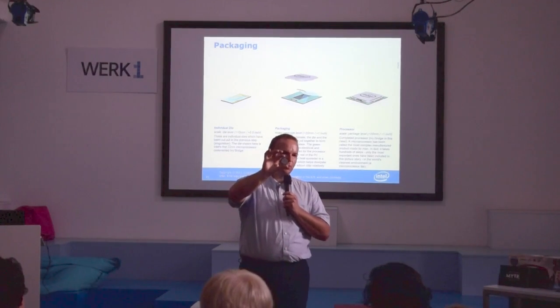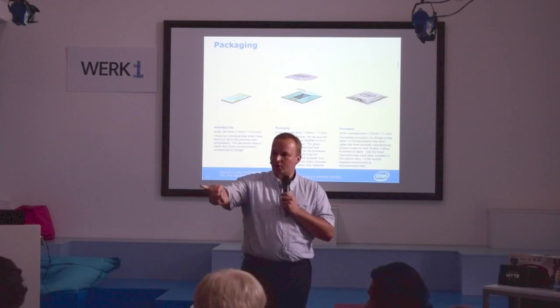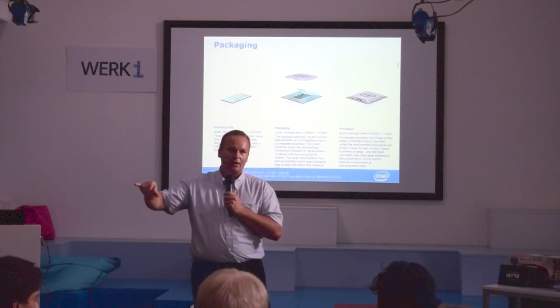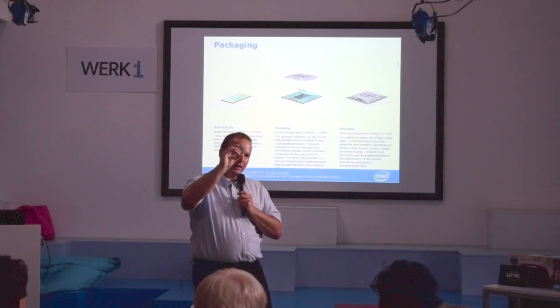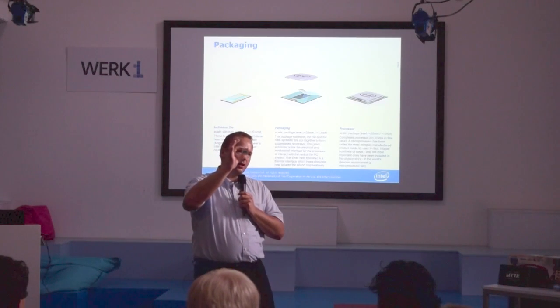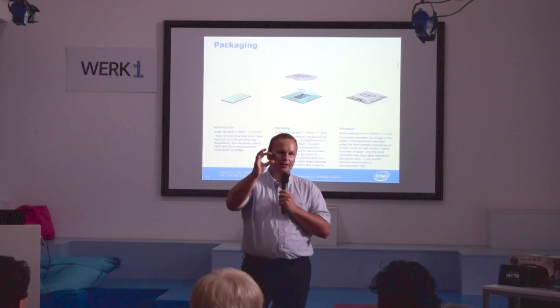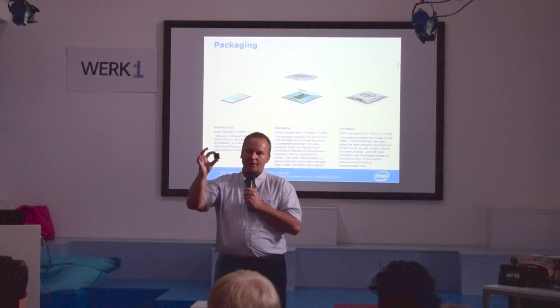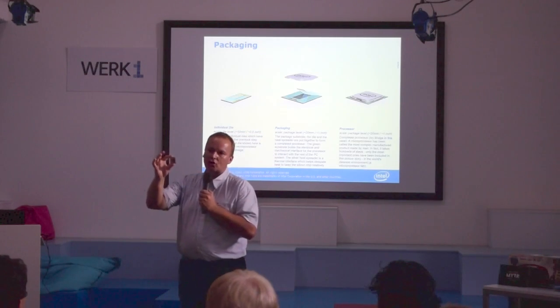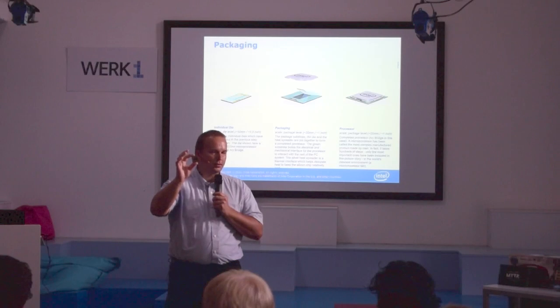That's the so-called heat spreader. It protects the die which sits underneath. If you look at that wafer, one of those rectangles sits underneath the metal cap. The backside of the processor has those so-called LANs. In the past we used pins, now it's LANs. It's basically contacts that are used to connect the processor to the motherboard and to connect it to the outside world.